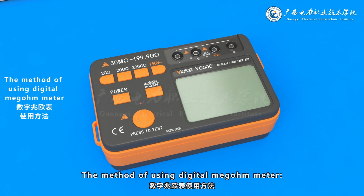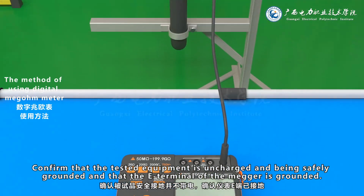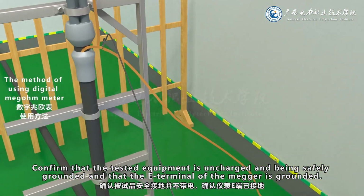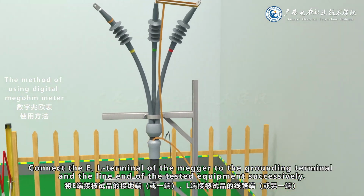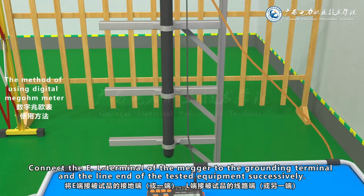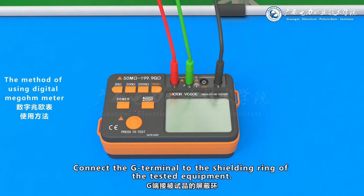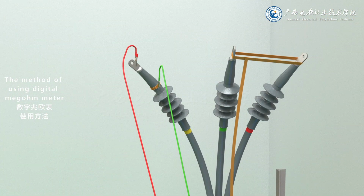The method of using digital Megger meter. Confirm that the tested equipment is uncharged and safely grounded and that the E terminal of the Megger is grounded. Connect the E, L terminal of the Megger to the grounding terminal and the line end of the tested equipment successively. Connect the G terminal to the shielding ring of the tested equipment.